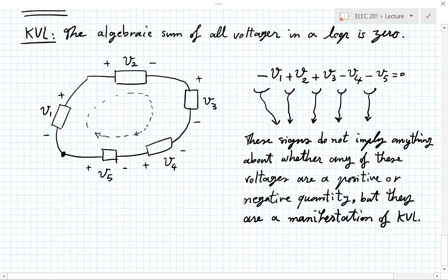But this is it. This is KVL. It's a simple yet very profound concept. And last time, as I said, this really can be shown by the fact that if you assume that voltages are well-defined quantities, and that each of these nodes does have indeed a well-defined voltage with respect to a reference that you've chosen somewhere. We will come back to that notion of node voltages and a reference node later on. And that's something that I'm sure you have all encountered.